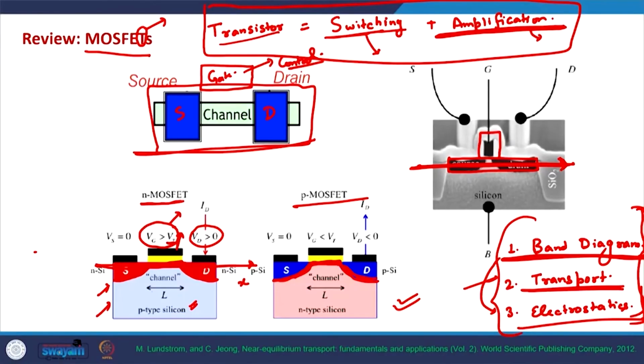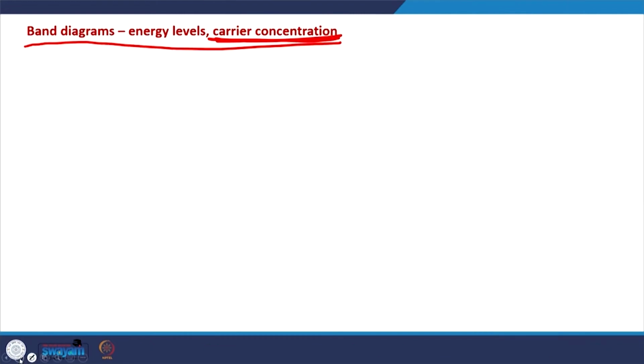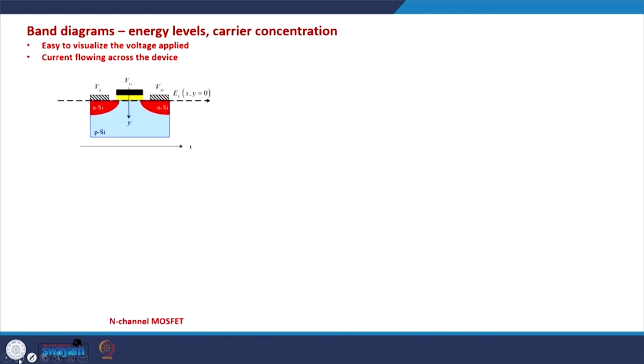So there are sort of two junctions in this direction that we will encounter if we traverse from source to the drain terminal. Okay, in the X direction, let's say, if we are taking the case of NMOS, in which the channel is N-type, the body is P-type, we have N-type source contact, we have N-type drain contact, and this direction, the direction of the current, is taken to be the X direction.